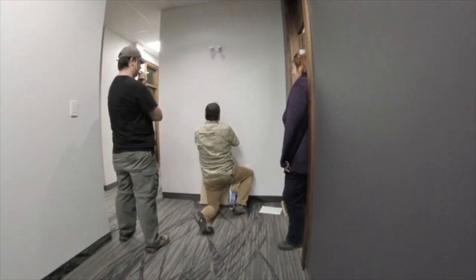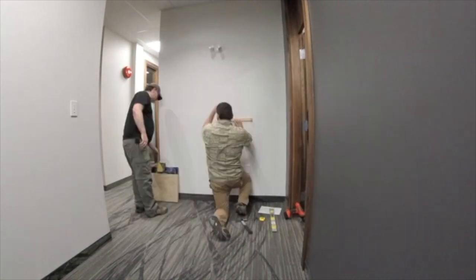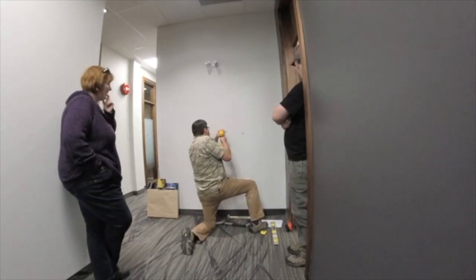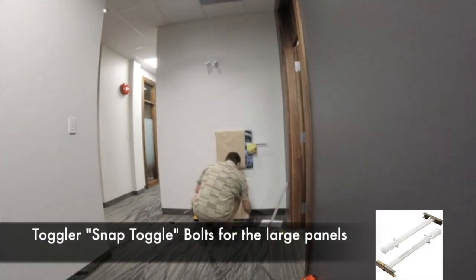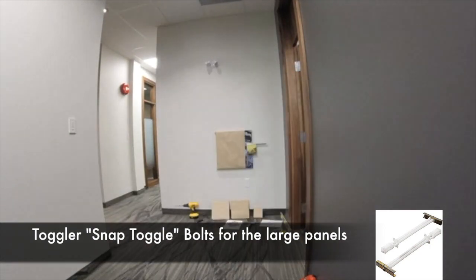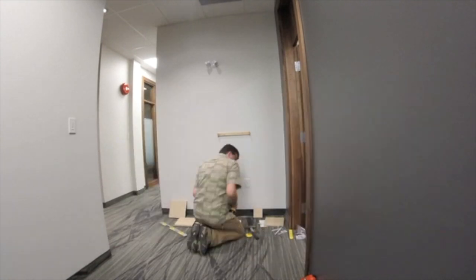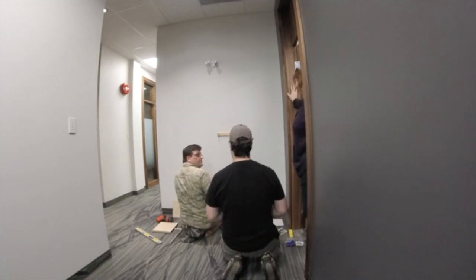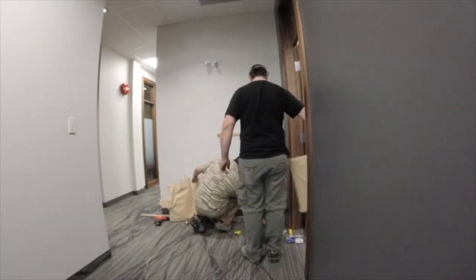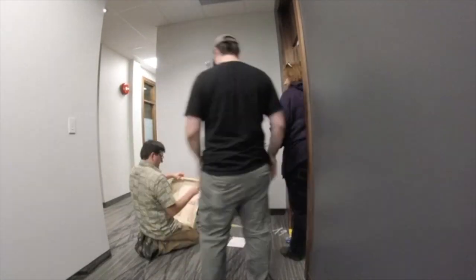So finally, it was installation day. We had some very detailed written instructions, and we were very carefully measuring to figure out where the holes were going to go for the cleats. I'm drilling holes here for the snap toggle bolts that held the larger pieces in place. It was really important to get the positions of these first wooden cleats just right, because everything sort of spreads out from there. So I was lucky to have the help of 2 much more experienced art hangers, especially at locations outside of the gallery.